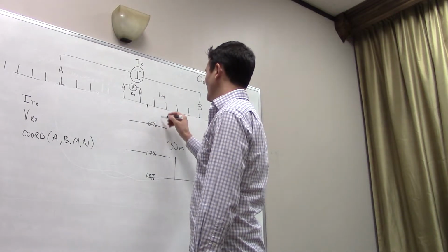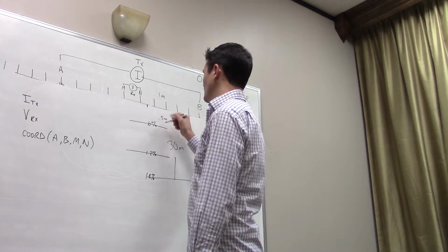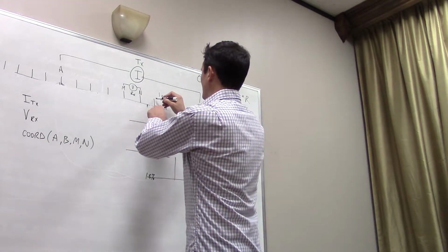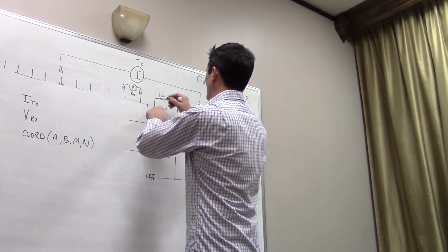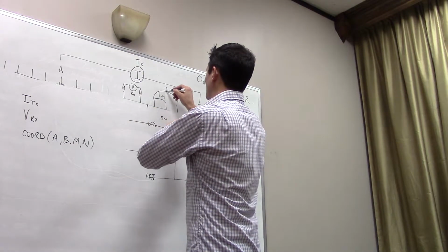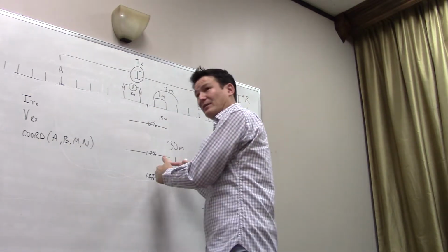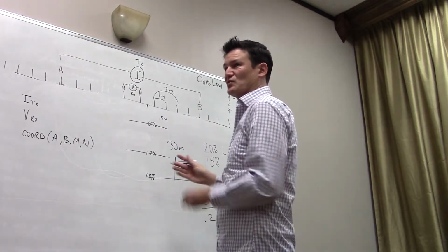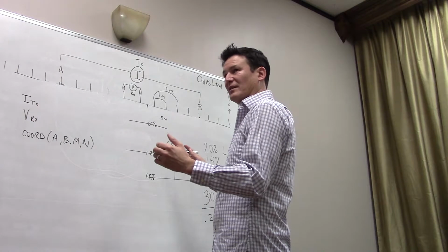Then you're going to have about 0.5 meter resolution here, right? But to get down to here, you may have to increase to 2 meters to get down deeper, because your signal disappears as A and B get larger, right? So it's a continuous give and take here.